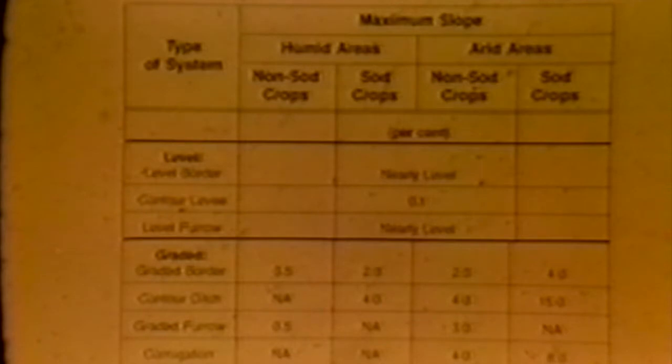The slope of your field is critical when selecting a surface irrigation system. If the farmer's field slopes are practically level, less than 0.1%, use one of the level types of systems that has a minimum of land preparation. If the field has more than 0.1% slope, use one of the graded types of systems. A competent person must lay out whatever type of surface system selected if it is to provide satisfactory irrigation service to meet the needs.